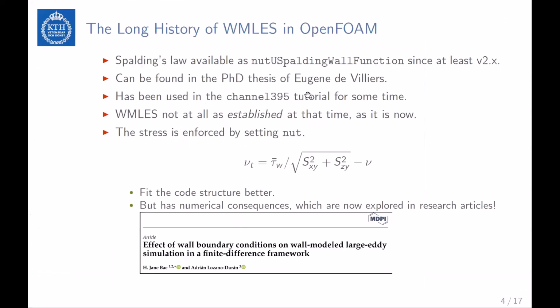Basically, I just made a short introduction of what wall-modeled LES is, and now we're talking about how long it's been in OpenFOAM. And there's been this channel 395 tutorial for LES in OpenFOAM back in the days. I think it's renamed now, but that one did use this wall function. Now, it should be said that at that time, the concept of wall-modeled LES has not been as strictly crystallized and defined as it is now. So I would argue that the channel 395 wasn't really a wall-modeled LES configuration, but that's beyond the point.